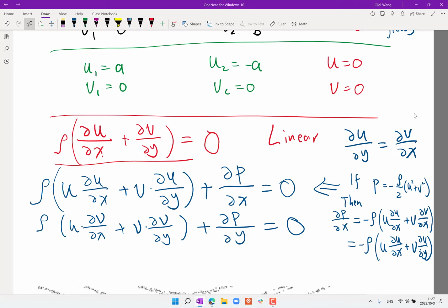Okay, so what does this mean? This means for incompressible potential flows, we get this incredibly nice property that if you add two flow fields, you get another valid flow field. That means we can just add up different flow fields to make up various more and more interesting flow fields. And this is practically what we'll be doing for the entire week, right?